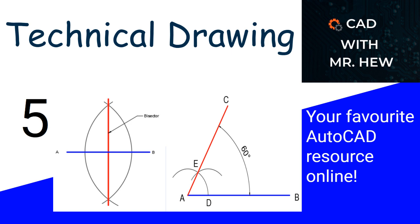We have come to the end of today's video. In today's video, we bisected a given line AB. We constructed a 60-degree angle to a line AB at A on the line. And in the next video, we'll be showing you how to bisect a given angle. So we look forward to seeing you in the next video, video 5.